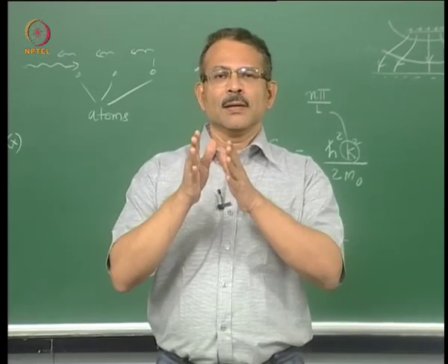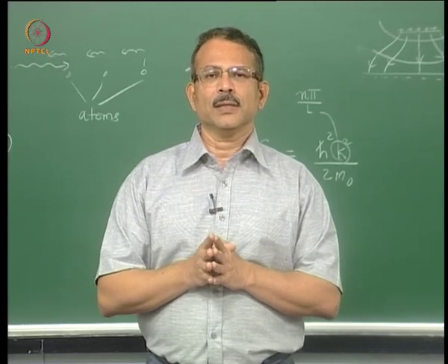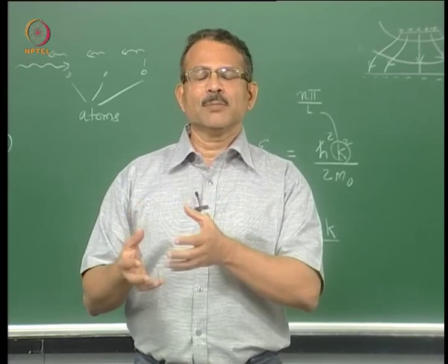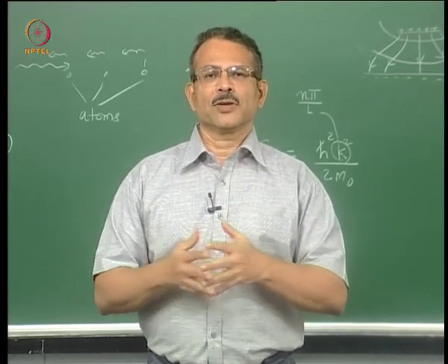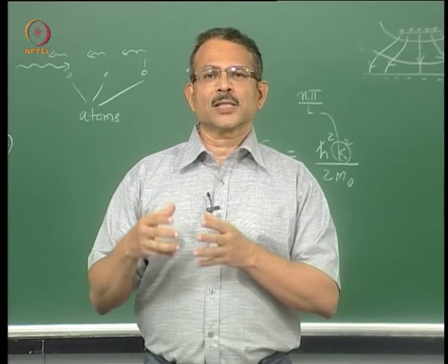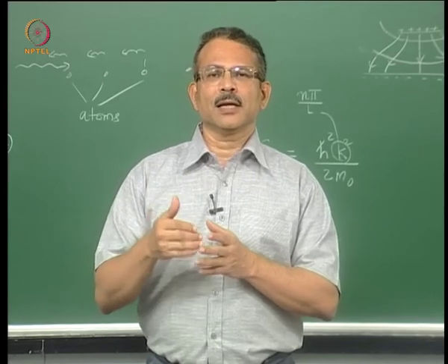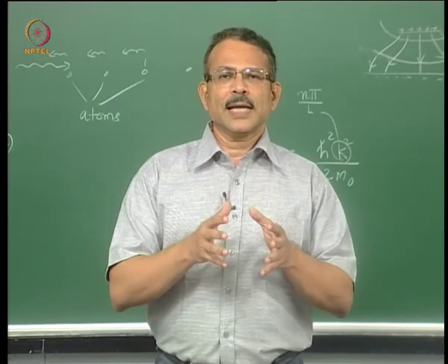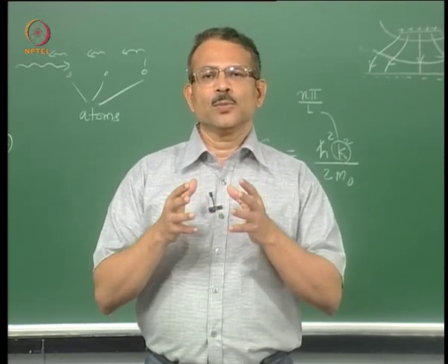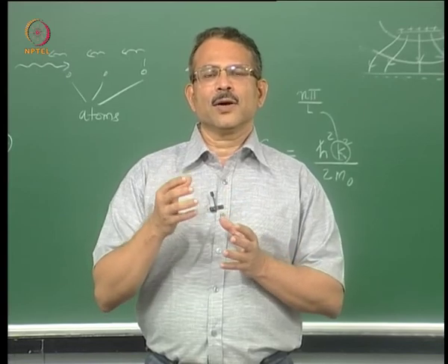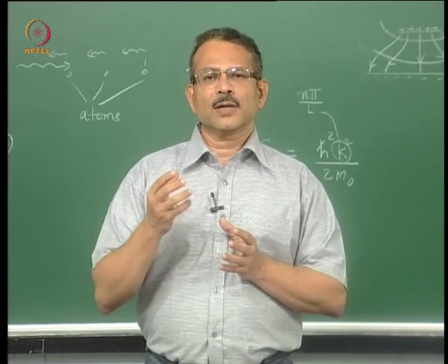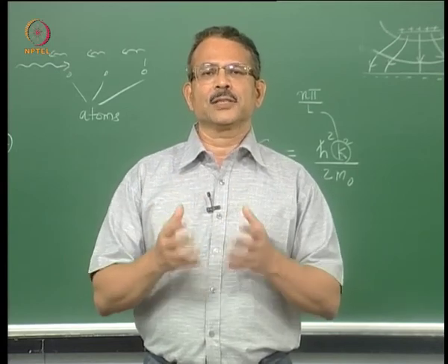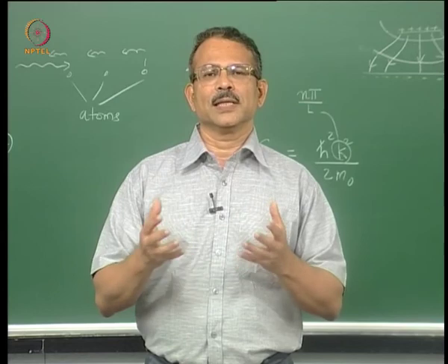in the crystal, at any x for example, the allowed energy as a function of the crystal momentum of the electrons. Normally the crystal momentum is represented in terms of the wave vector k, and therefore this is called the E-k diagram. The E-x diagram helps us to analyze the electron and hole distributions, the electron and hole current density distributions, and electric field and potential distributions in the device as a function of space and time.